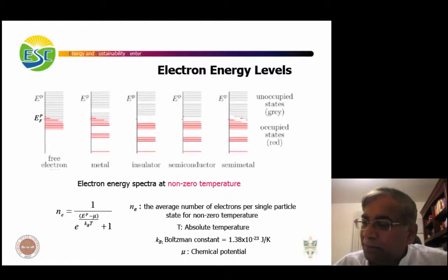Valence band electrons can be moved into holes, which can have a preferred direction of motion. When a hole is placed, electrons can move into that hole. These electrons then leave behind holes that have the opposite direction of motion. It is often more convenient to think of the moving holes instead of the electrons as the electric current carriers in the valence band.